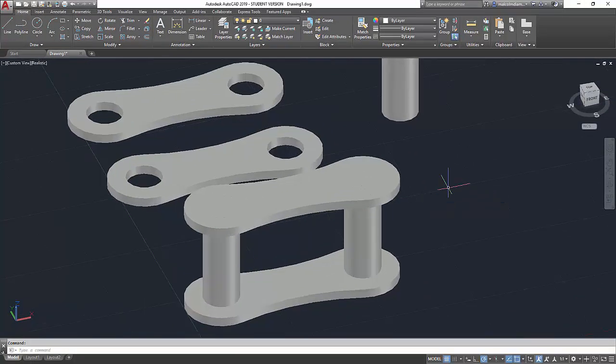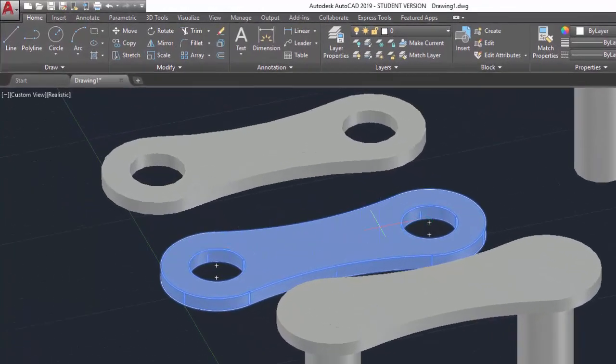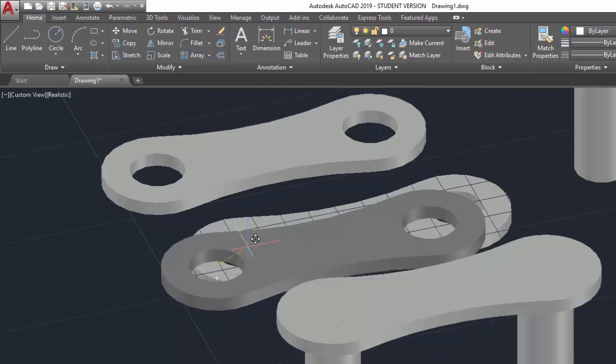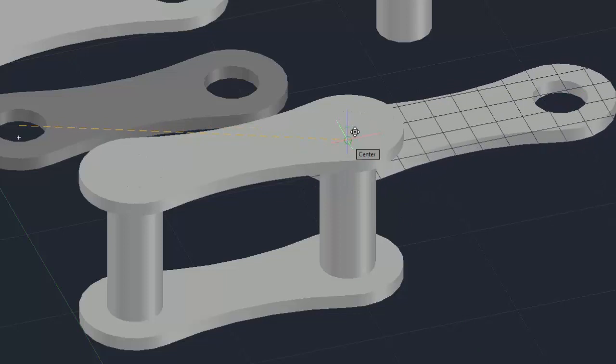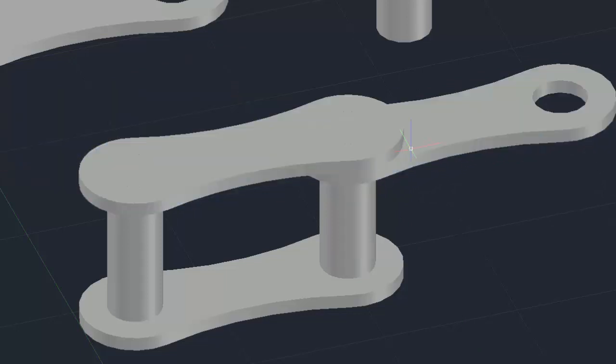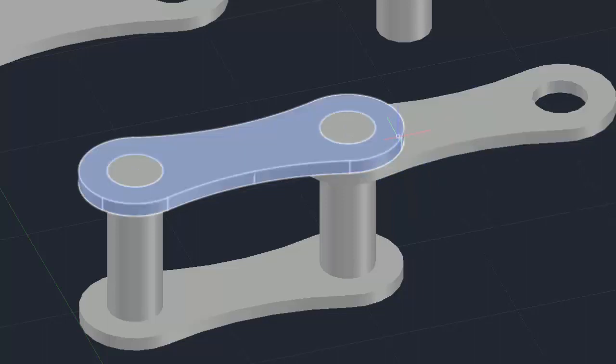Okay. Now, the top section, the top of this plate, this plane here, needs to go underneath this one. So I'm going to move, left click this plate, and it will be the upper side, the top side of this, that mates with the underside of this one. So I'm going to grab it by its top center point and look at these 2 center points here and place it to the bottom of those 2 center points. And now you can see that this one fits snugly underneath that one there.